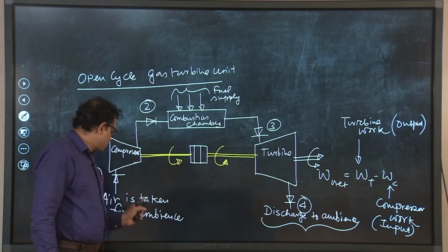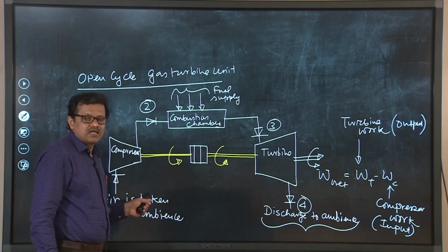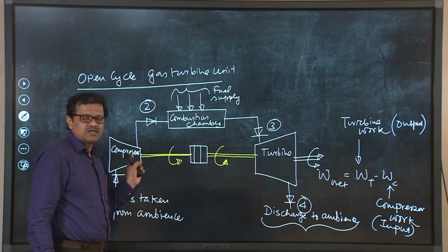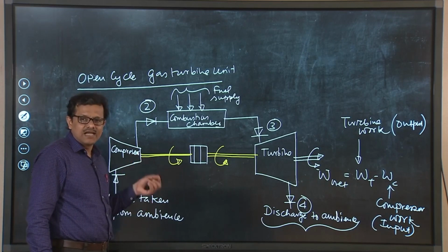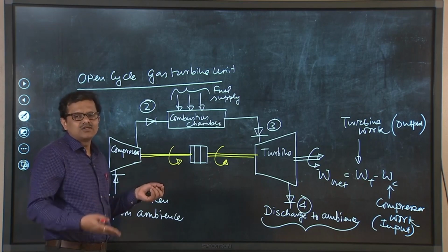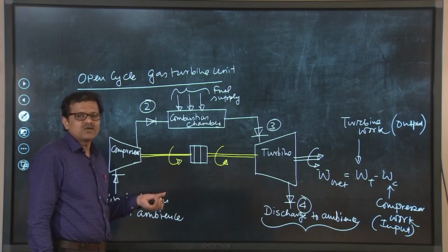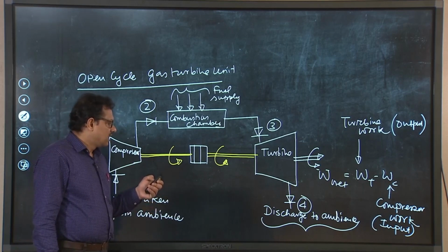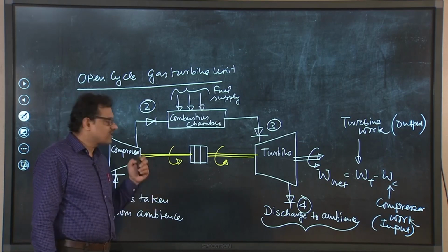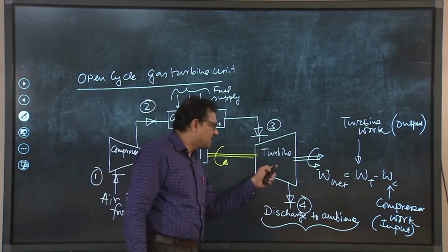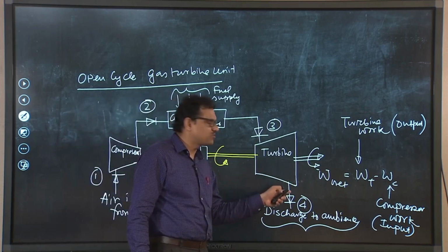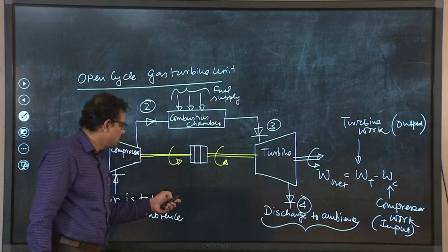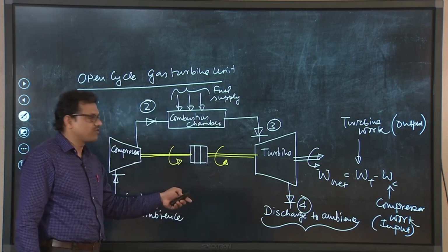What is done? So, we need to ensure that air that is drawn into the compressor should be properly screened to eliminate those foreign particles. So, high quality filters are needed, but if we somehow can recycle back the air that comes out or gas that comes out from the turbine into the compressor again, certainly we have to release certain amount of it.